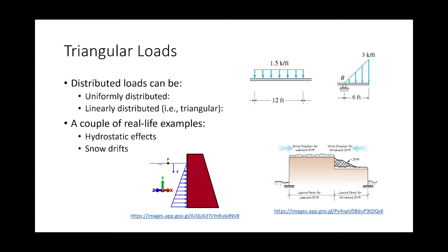And so you get a bunch of snow on the roof, and then the wind blows. The wind bunches up that snow along one of those walls or along one of the appurtenances, and suddenly, by golly gosh gee, you have a triangular load. So that is a real example of triangular load distribution.